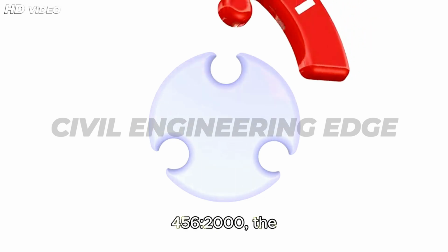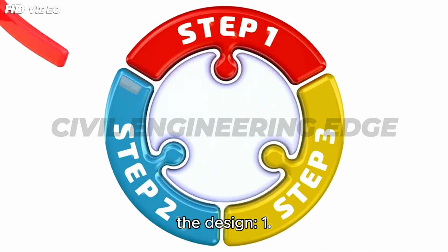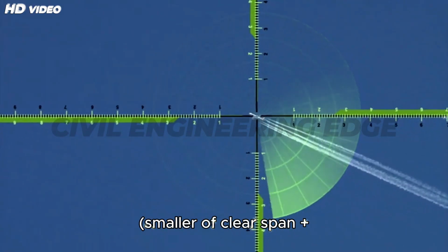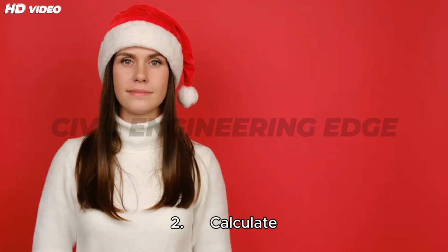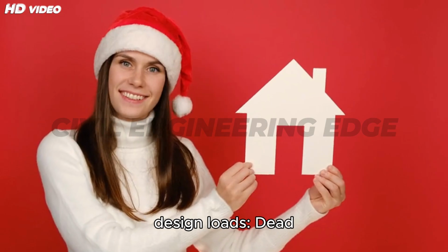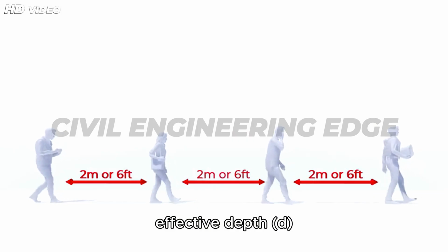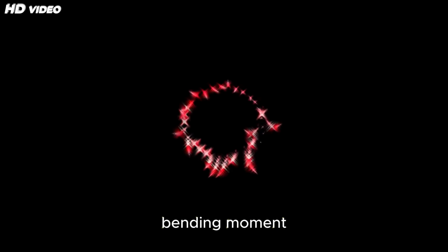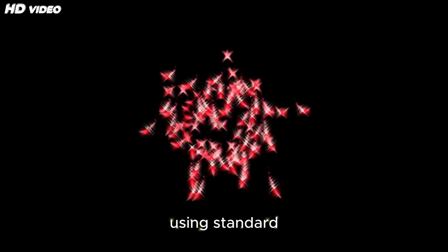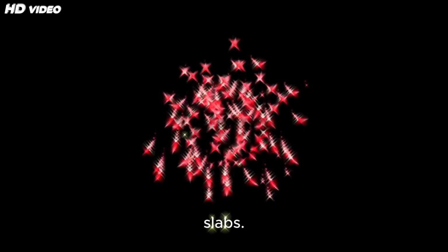As per IS 456:2000, the following steps are involved in the design. 1. Determine effective span: smaller of clear span plus effective depth or center-to-center distance between supports. 2. Calculate design loads: dead load plus live load plus finishes. 3. Assume effective depth d based on span-to-depth ratios. 4. Compute bending moment using standard formula, M = wL²/8 for simply supported slabs.